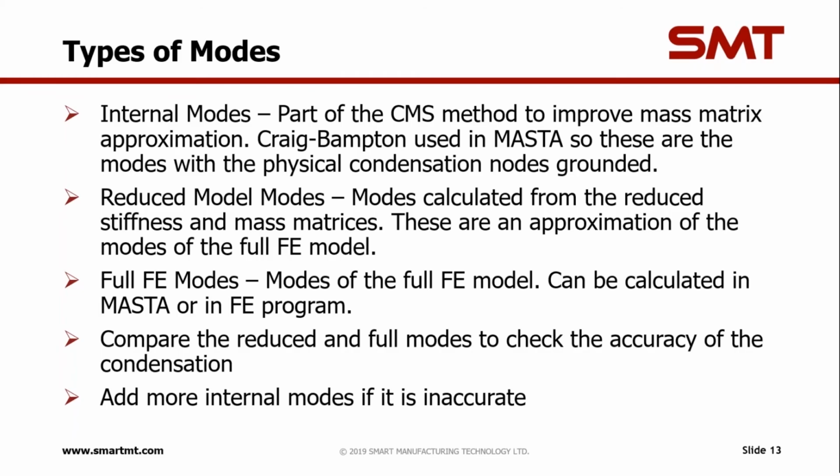On the mode analysis tab, we also have two other sets of modes. The first of these is the reduced model modes. These are calculated from the reduced stiffness and mass matrices, and they show the approximation of the modes of the full FE model. We also have the option to calculate the modes of the full FE model as well. Ideally, we'd like the reduced model modes and the full FE model modes to match up to some frequency of interest. If they don't, then that's when we add more of the internal modes.